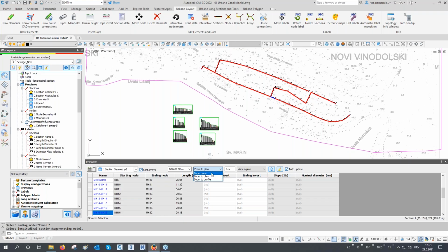I will turn off zoom and I will say mark both. And now you can see for each section where we have it in plan and in which profiles. So now you see that this section is appearing in multiple profiles. I like to have this as marking plan only. And like I said, if you want to clean this temporary graphic, just click on a broom.